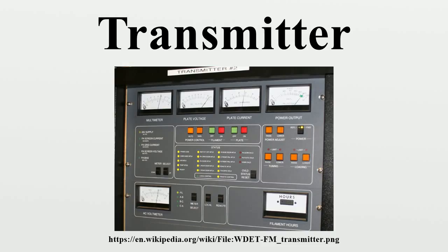A radio transmitter is an electronic circuit which transforms electric power from a battery or electrical mains into a radio frequency alternating current, which reverses direction millions to billions of times per second. The energy in such a rapidly reversing current can radiate off a conductor as electromagnetic waves. The transmitter also impresses information, such as an audio or video signal, onto the radio frequency current to be carried by the radio waves. When they strike the antenna of a radio receiver, the waves excite similar radio frequency currents in it. The radio receiver extracts the information from the received waves.